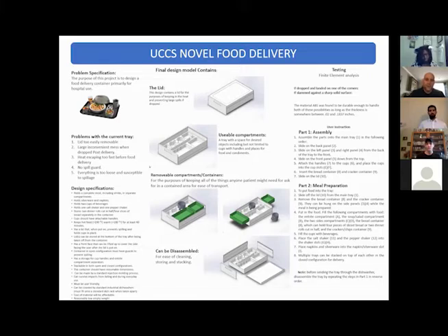All of these things we worked on over the course of a couple of months, trying to figure out different dimensions and size constraints that would fit within the overall design of, I think it was, 11 inches by 18 inches. We came up with this final design with the sliding walls and back in order to conform to one of the requirements, which was that the design be injection moldable. In order to do that, we couldn't have certain undercuts. The thickness of certain parts needed to be within certain tolerances, and the tray overall needed to be made out of a plastic that is usable in injection molding, in order to make the tray more flat for travel and things of that nature.